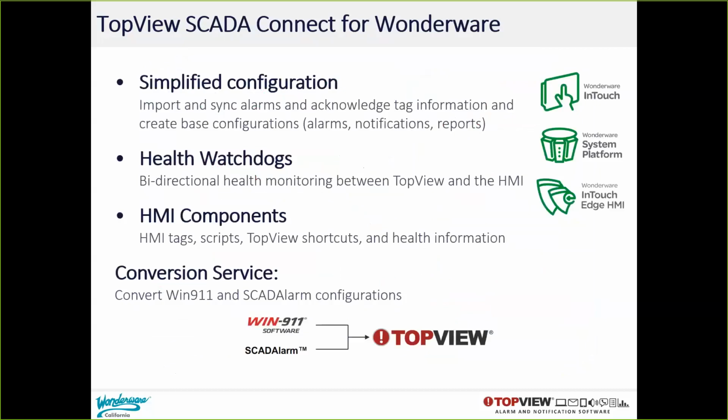The TopView SCADA Connect module for Wonderware simplifies the integration of TopView and your alarms by providing import and synchronization of your current Wonderware alarms. Bidirectional watchdogs can be enabled that allow TopView to monitor the health of your SCADA system while also allowing the SCADA system to monitor the health of TopView. TopView's HMI components give you a view into TopView's health and also quick access to various TopView applications. And for those coming from other notification products, we offer a service to import your current Win911 or SCADA alarm settings into TopView, which also generates reports of any problems or issues with the existing configurations.